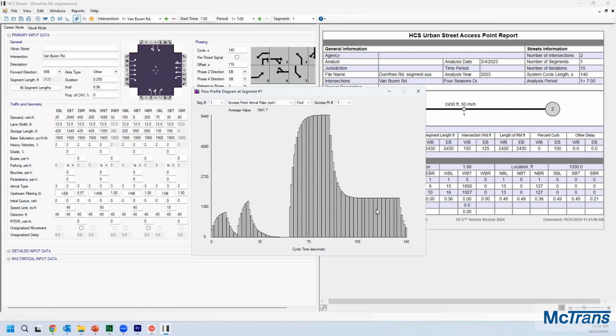But on the other hand, when you have some peak blockage, that means for the remainder of the cycle, if you look at the first half here, you'll see some periods with low volumes, and those low volume periods create several gaps, several opportunities for vehicles to enter the intersection and clear the queues. So that is the part of the blockage that can actually increase capacity. It doesn't mean every single input will increase capacity. It really depends on the proportion of time blocked.